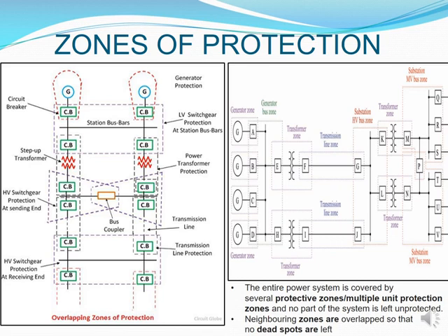Then if we move away from the two transformers and look now at our bus coupler, you can say it's a bus coupler scheme if you want. In our bus coupler, you can see that it is involved in two different schemes. You've got the two circuit breakers on our left hand side, and then you've got the breaker that is the actual bus coupler. So that is the one side that's looking after this bus coupler of ours.